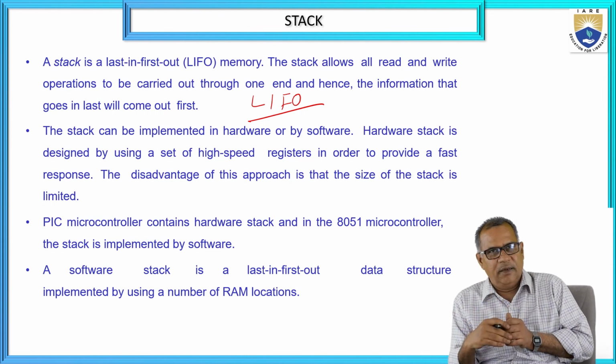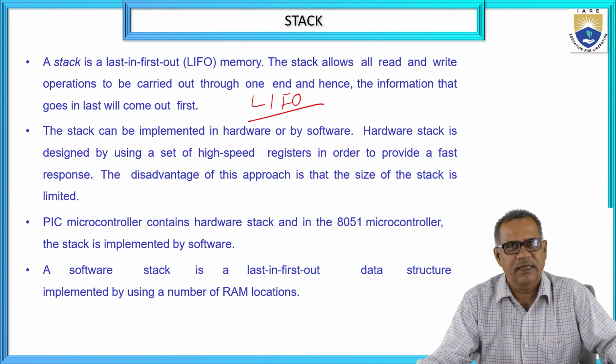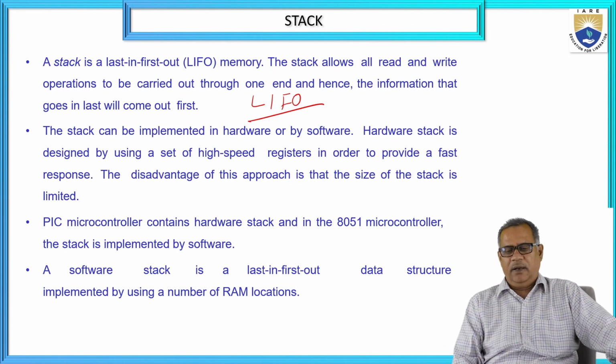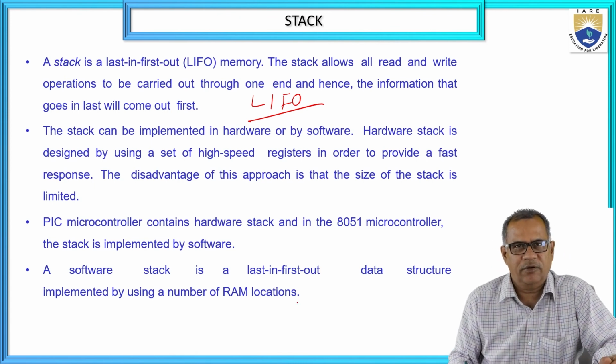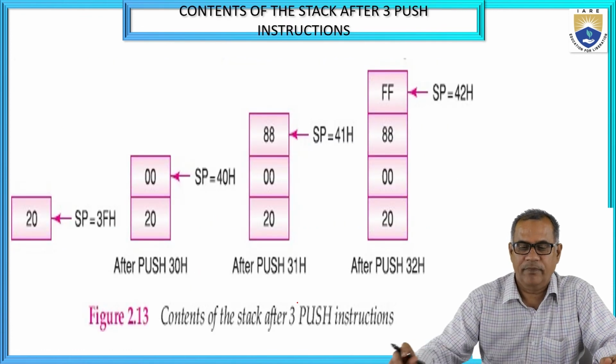The PIC microcontroller contains a hardware stack, and in the 8051 controller, the stack is implemented by software. The software stack is a last in, first out data structure implemented using a number of RAM locations. And the general purpose RAM of the 8051 microcontroller is used for stack purposes.